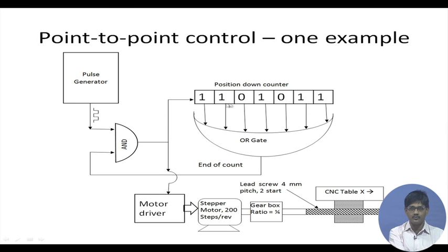That means it can be reduced by every pulse which is coming in at this point, which is called the clock input. So, if a pulse arrives here, it reduces the content by 1. So, after one pulse comes in, this will become 11011010. This way it will go on reducing for each and every pulse which comes inside. So, ultimately it will become 0. When these are containing different bits, they are also input to an OR gate.